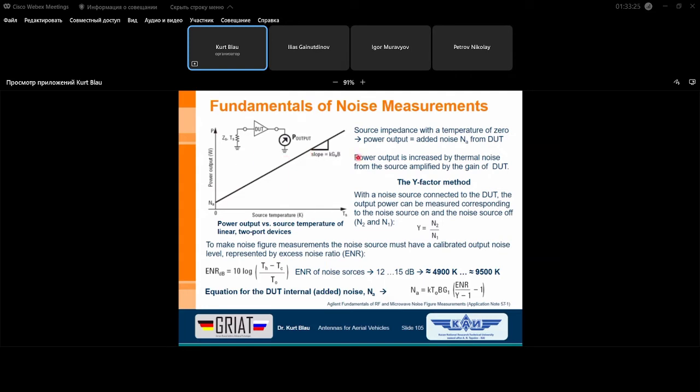And now let's discuss a tricky method based on these things. In practice, it's not very convenient to heat up the source resistance by fire or whatever means of physically increasing the temperature. In the meantime, we have another interesting method to realize this higher source temperature with a semiconductor device, namely an avalanche diode.